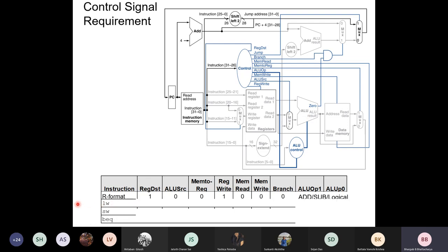Well, so we do this. You have correctly said what should be the control signals here. And ALU op 1 and ALU op 0, there should be some 0, 1 signal here, and that depends on whatever instruction you are executing in this R type, like it may be add operation, subtract, or maybe logical and or or and so on. Well, so that's done, right?